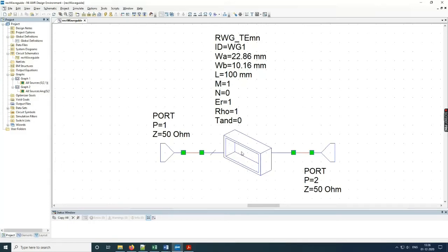So that is the length of the effective transmission line. If I were to use this waveguide as a transmission line, the length of the transmission line would be about 10 centimeters. And the mode that I'm using is the TE mode. This is the dominant mode which I want to use. Depending on which mode I'm exciting, I can change the values of M and N. And since it is an air-filled waveguide, the epsilon inside the waveguide is 1. Now let us see, if I am feeding some signal on one end, what signal I am receiving at the other end, as a function of frequency.